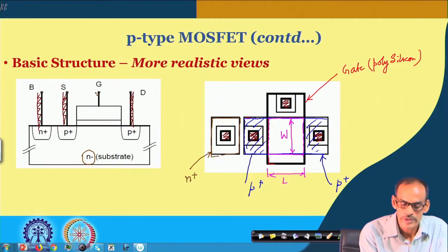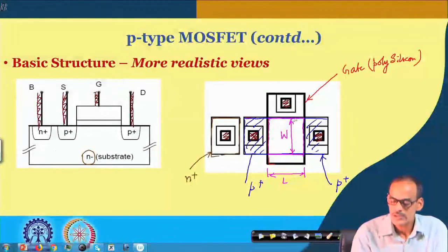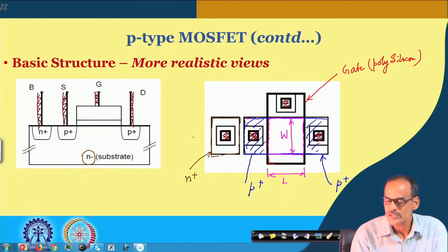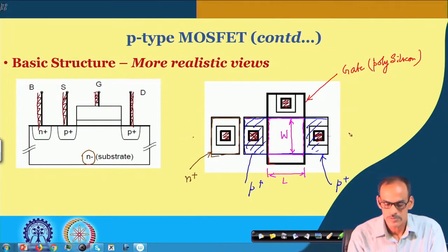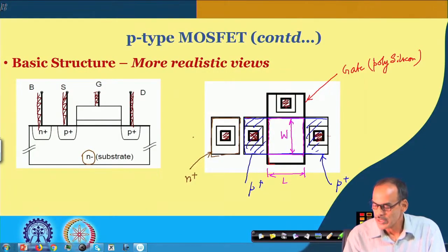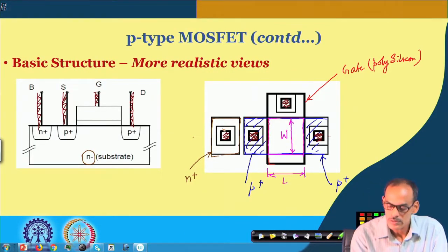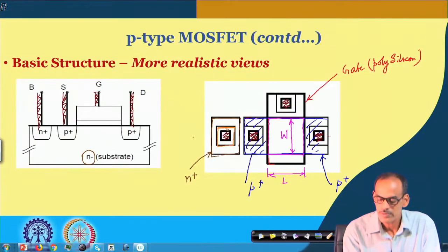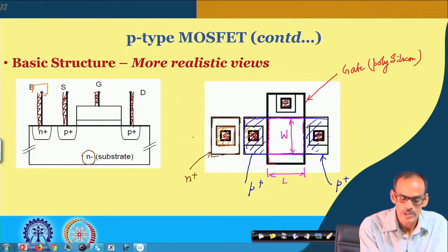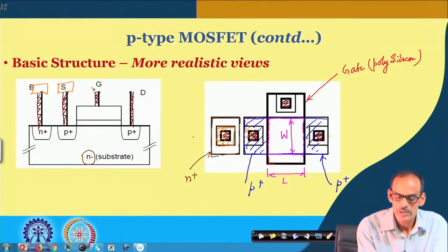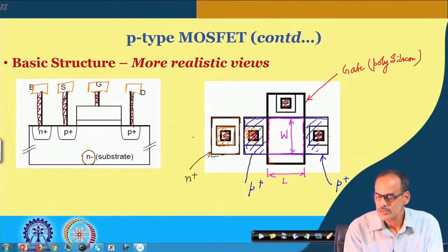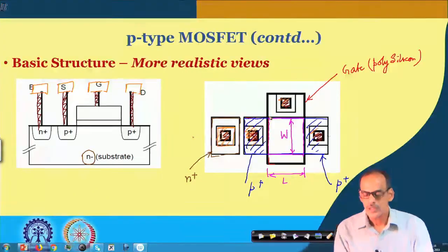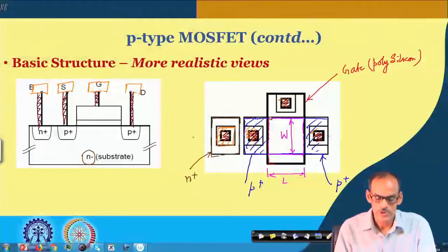And then also we do have the gate contacts here, but this is not really along this cross sectional view that we have discussed in the previous class. And on top of that there are different rectangular boxes here. If you see here, this portion is basically representing the metal 1. So, on top of this contact we do have the metal 1 here, we do have another metal 1 here, and so on. So, this portion is metal, this portion is metal, and so on. So, that is a little bit about the top view of the actual device.